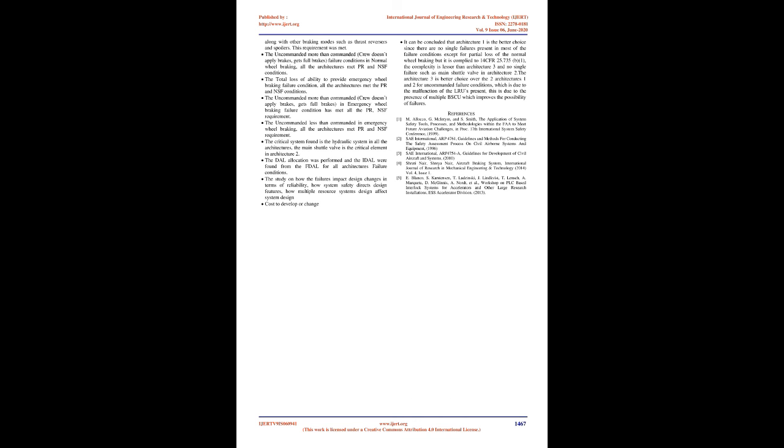The crew not aware case comes under crew aware, since all the failure conditions are inherently detectable. The analysis was performed for the entire flight phase without considering the time at risk. This means the actual probability of failure is better than the probability of failure obtained in the software. The brake failure is applicable to only one flight as it is always checked during takeoff and previous landing.